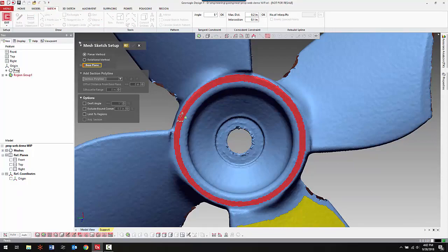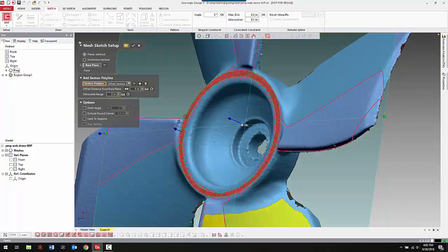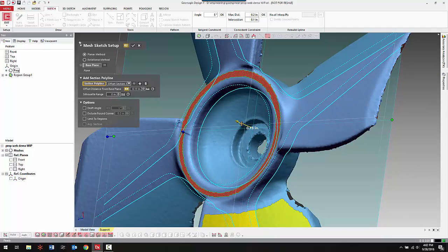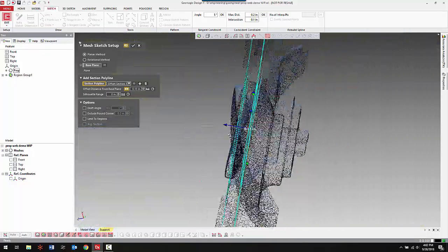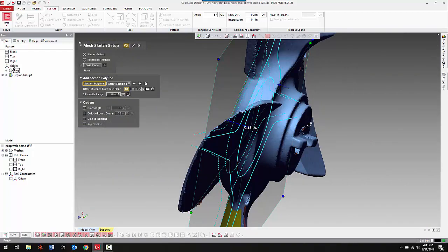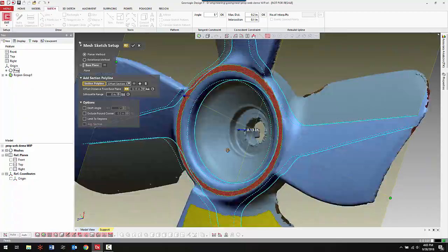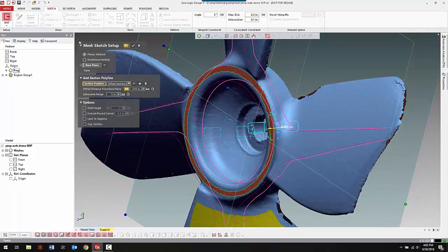based on this plane. And when I do that, you can see it's kind of virtually cutting through right at the top surface there. So what I'm looking to do is drag this arrow into the part a bit, and I can see that there's a circular profile, and that's going to help me establish the center of the part. And there's also a feature down here that I want to help when I clock the part for the x-axis. So I want to take another section, and I'll go ahead and drag that arrow further down into the part until I can see that feature I just pointed out. That looks good. So I'll say OK.